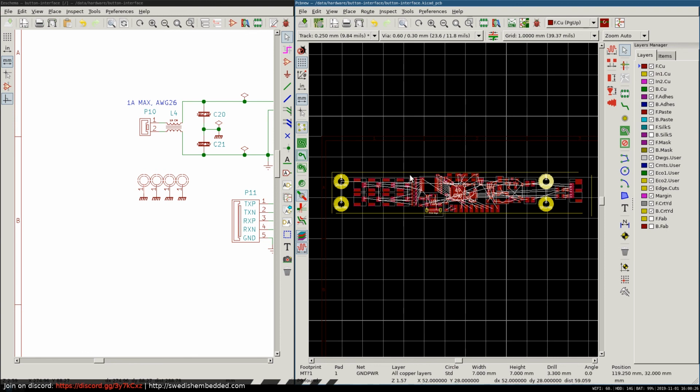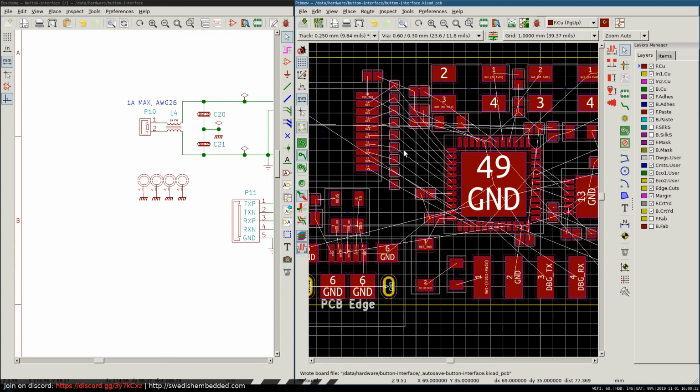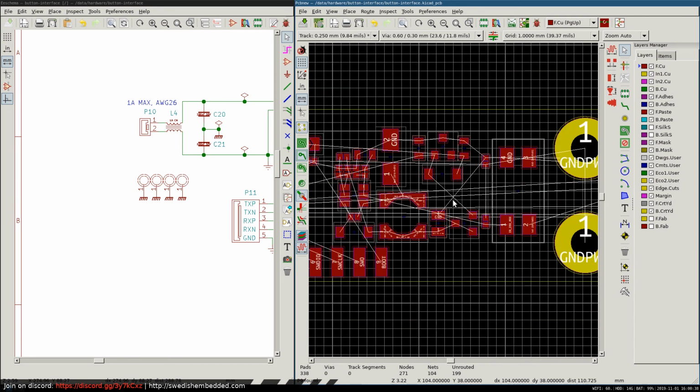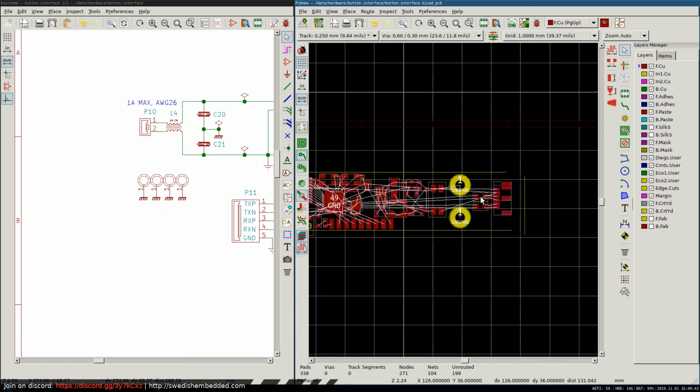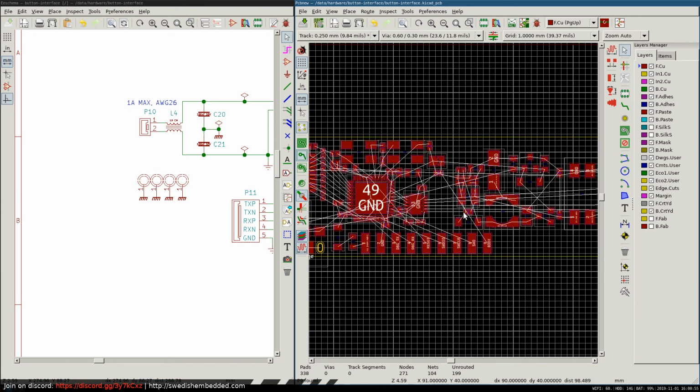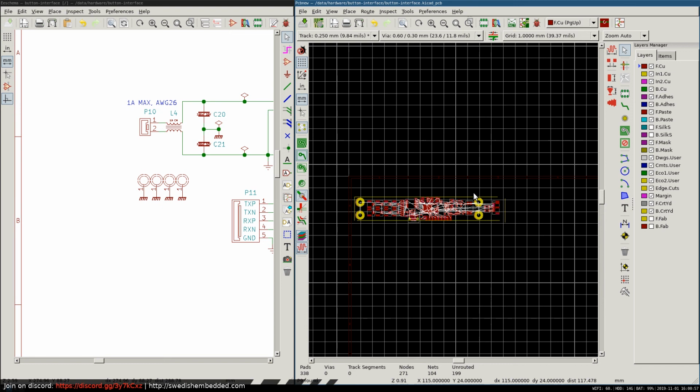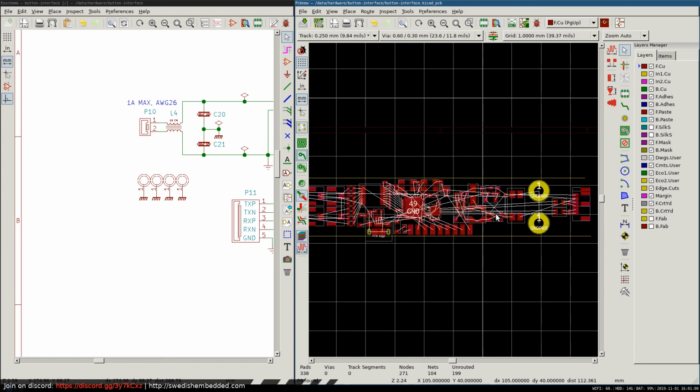And then, of course, I have to start routing this PCB, and I'm probably going to discover some places where I have to move components a little bit to make sure that there is enough space. But I think for the most part, this is going to look very good. And this one will go on the back, just straight to here. The transmission lines are going to be on the other side of the ground plane. So they're going to be a little bit shielded from this regulator. Shouldn't be a problem.